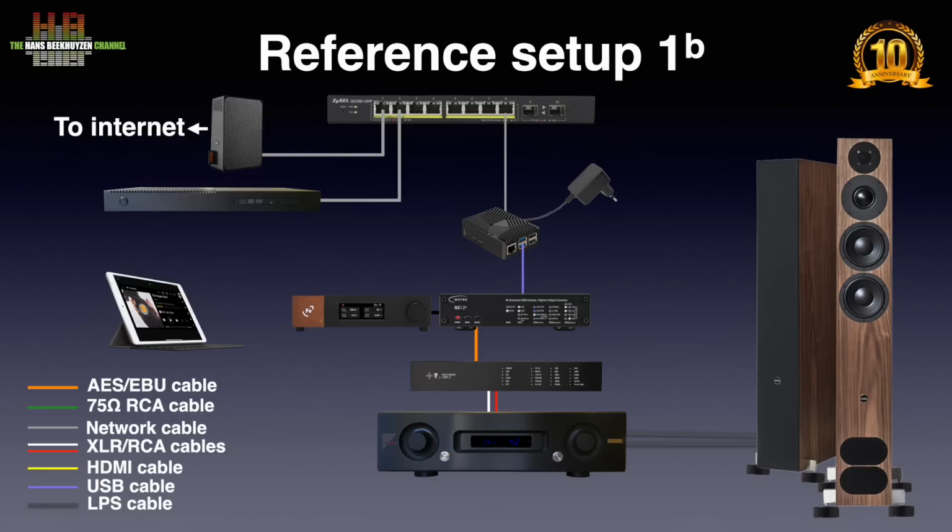This is a hybrid power supply using both switch mode and linear circuits. I would have loved to use a cheaper one. The Hypsos cost €1200, but this was the only power supply I have that does 9 volts. There is a third option to power the MC 1.2 Plus, and that is over the USB power line, but since that would feed the usually dirty power and ground to the MC 1.2 Plus, I didn't try that.